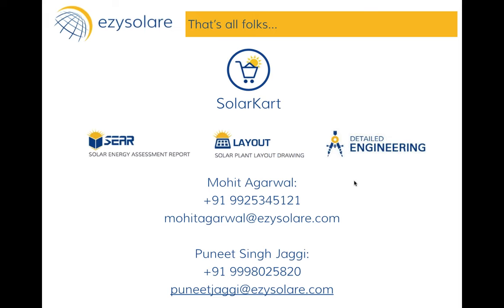The other thing is that tilt is sometimes also dependent on the total area that you have, because if you have a 30-degree tilt, then there's going to be some shadow behind it. In case you have a 25-degree tilt, the shadow is going to be smaller. In case you have a 10-degree tilt, it's going to be further smaller. So when you have less area available and you want to fit in larger capacity, you keep decreasing the tilt so that you can fit in one row behind the other without casting any shadow.